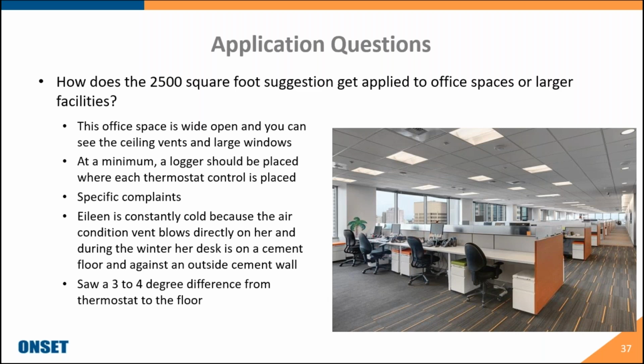And again, if you have any other people who are complaining about it, you can always place something near there. But some key things that do affect temperature are: are the windows open? Are they tinted? Are they treated? Is it allowing too much sunlight coming in and heating up one part of the building versus not the other? Things of that nature. So you can really dive in deep to what's causing these thermal discomforts by just placing data loggers around the whole facility to get a better representation of what's going on in the different areas.